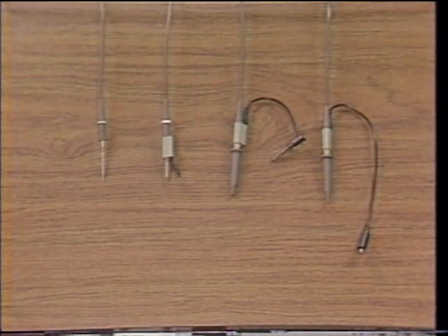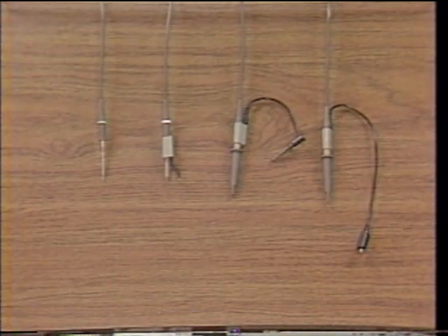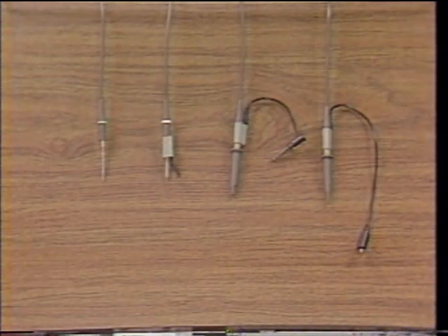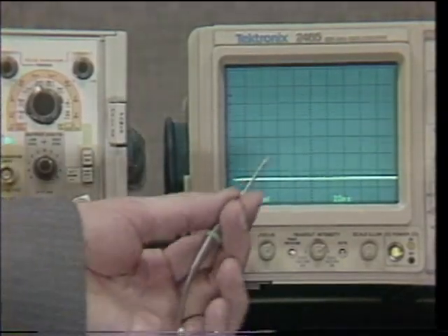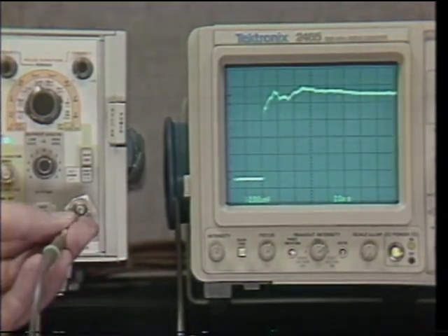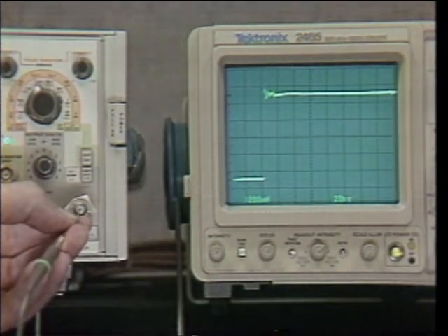Each of these configurations obviously has application advantages, but unfortunately, as we increase the length of the ground, the fidelity of the waveform is deteriorated. We'll now demonstrate the effect of each of these grounding techniques on a real signal. Let's begin with the coaxial configuration. Simply touching the signal to the center conductor of this BNC connector and grounding the shell,